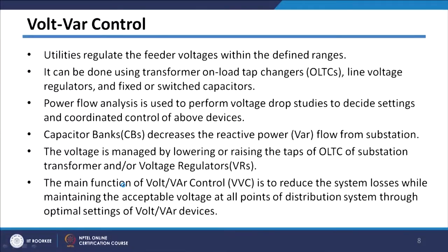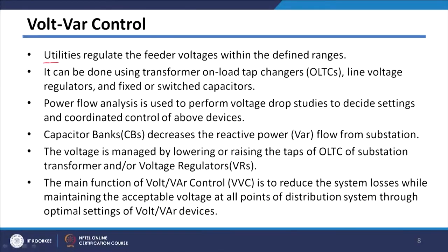Another important operational issue is volt var control. We know that utilities regulate the feeder voltages within the limit. We have seen that standards in various countries specify these limits of voltages. So voltages of the distribution system should vary within that limit. Therefore, I have written that utilities regulate the feeder voltages within the defined ranges,